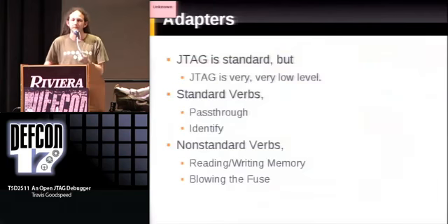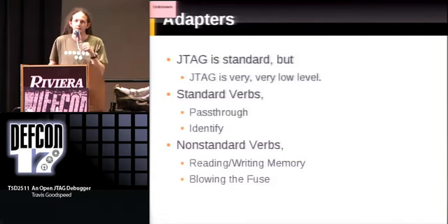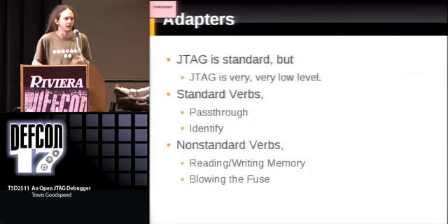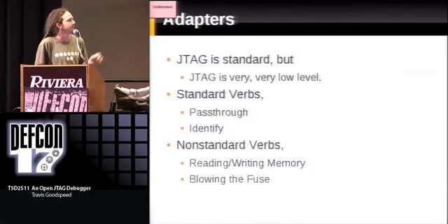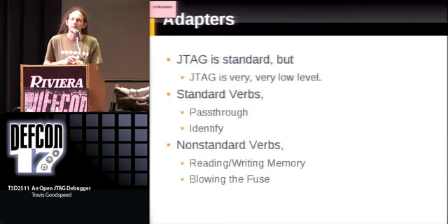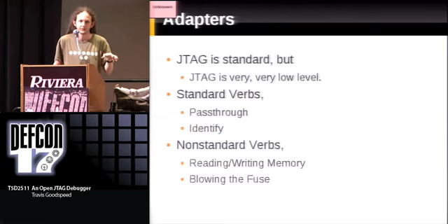or an adapter. This adapter will be connected to by your development environment, whether it's a commercial IDE or whether you're using open source tools. The standard itself only tells you how to populate 2 registers and then send a trigger for execution. So when I say that it's a standard, I don't mean that chips can be read and written in a standard way. The standard verbs only allow you to pass traffic from one chip to the next, or to identify a given chip. And there are a few others that are semi-standard that might be supported.